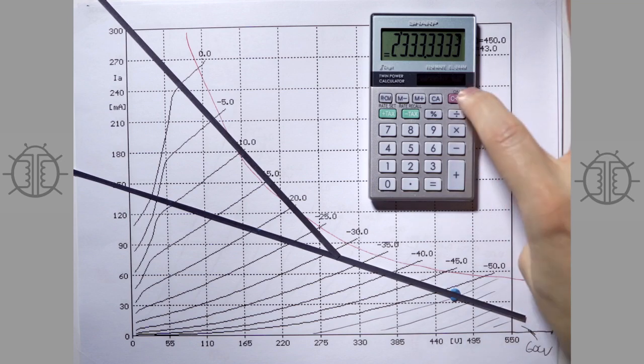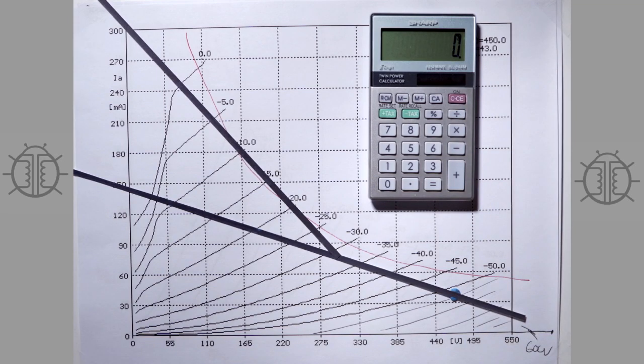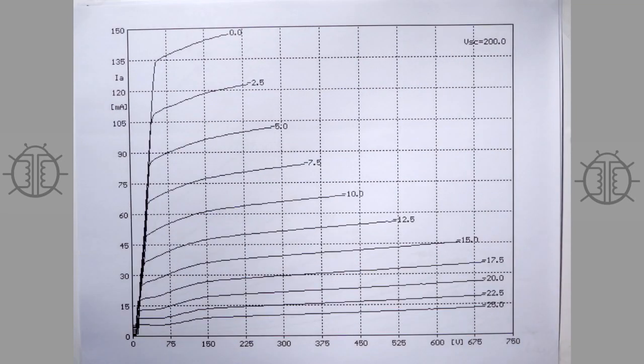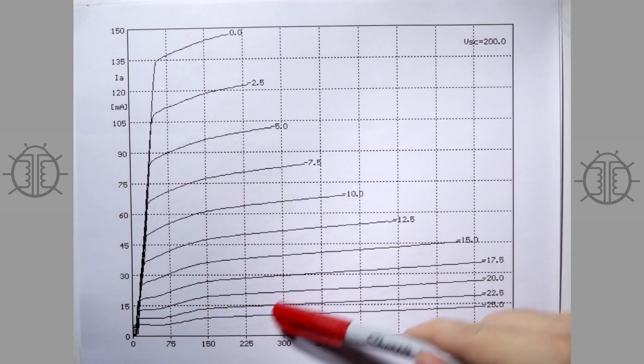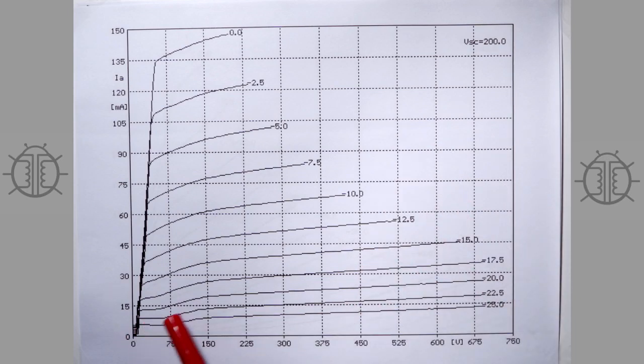All right, so next thing we're going to do is we're going to look at pentode curves. All right, so now we finally get into pentode land here, and you can see that the curves couldn't be more different. Before they were sort of voltage sourcey, kind of coming up like this. Now we're in current source land, where you basically have a pure transconductance that ignores the plate voltage to a large extent, and only gives you a current out compared to your voltage differential input.